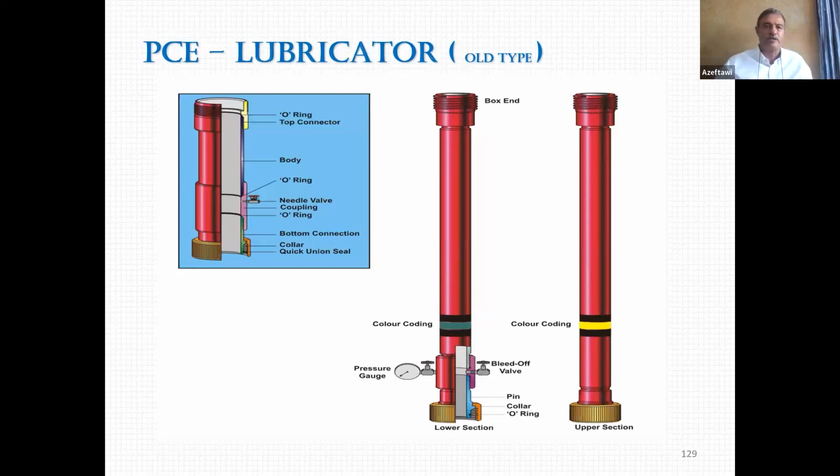Your tools could be stem bars, centralizers, knuckle joints. You can have running tools, shifting tools, kick-over tools, jars, spears, whatever. So these are bottom hole tools. The lubricator is mainly to accommodate the total length of the BHA.